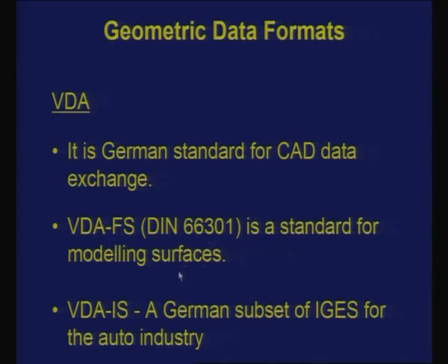Then there is VDA-IS, which is for solids. It is some kind of a subset of IGES, particularly followed in the auto industry, the automobile industry. So, these two are popular formats, and many software packages give an option of VDA too, but many times you may have to buy it, it may not be readily available. If I know that I have to deal with those firms where VDA is one of the preferred standards, so I may.